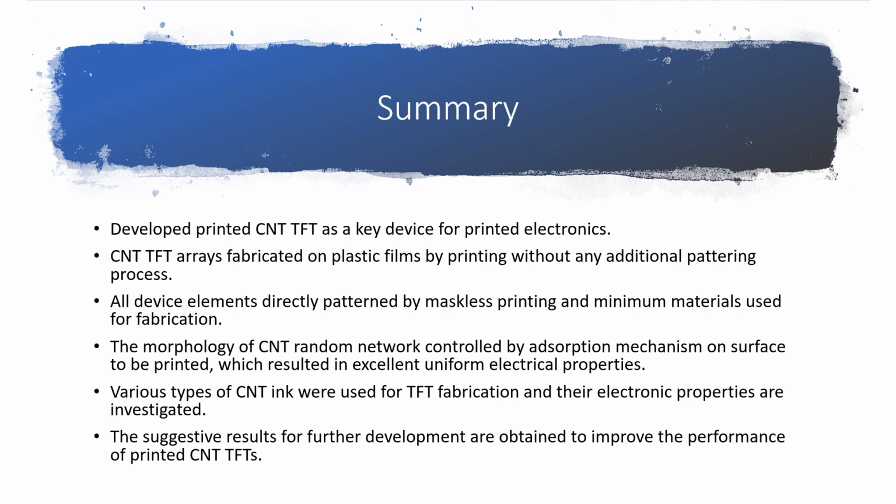During fabrication, the morphology of the CNT random network was controlled by an adsorption mechanism on the surface to be printed, which resulted in excellent and uniform electrical properties. Various types of CNT ink were also used for the TFT fabrication, and their electronic properties were investigated. The suggestive results for further development of the CNT ink were obtained in order to improve the performance of the printed CNT TFTs. Thank you.